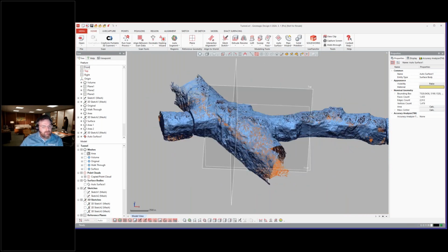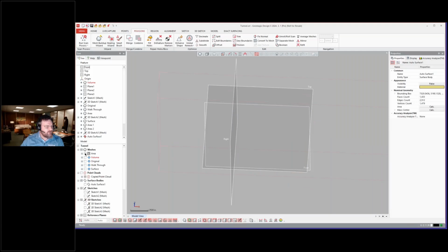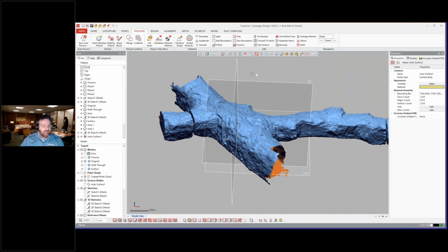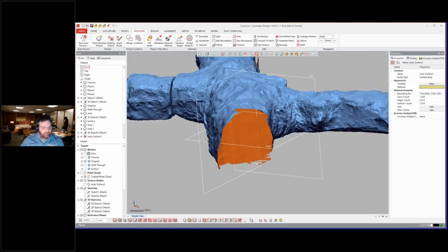And what you can do with this is it's a point cloud over here, but you have the ability in here to come over and merge and triangulate this object into a mesh. So I'll go ahead and turn that off, and we'll just show what the result is. So you can triangulate that into a polygon mesh.